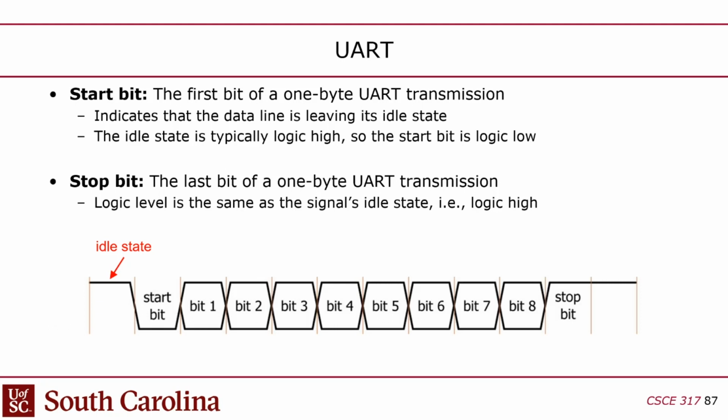Okay, so there's a start bit and a stop bit. The start bit is because the idle state of the bus is 1, logic 1. I don't know why they do that. This is a push-pull system. It's push-pull, so they didn't have to make the idle state 1, but they did.